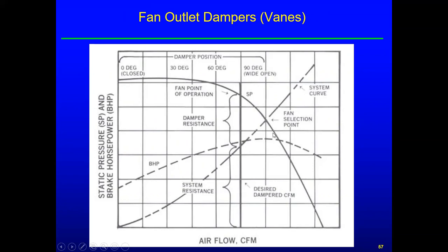We've kind of been over this a little bit. This would be the system resistance with the damper wide open. So this would be our fan selection point. We're going to close the damper, operate up here.